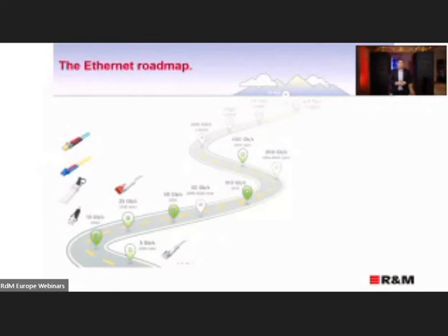Primarily, this application is running on category 8 for about 50 meters in channel, but it can run on some products of different producers, which were designed for category 6A, but the producer needs to give the warranty based on his own test in the laboratory, of course.